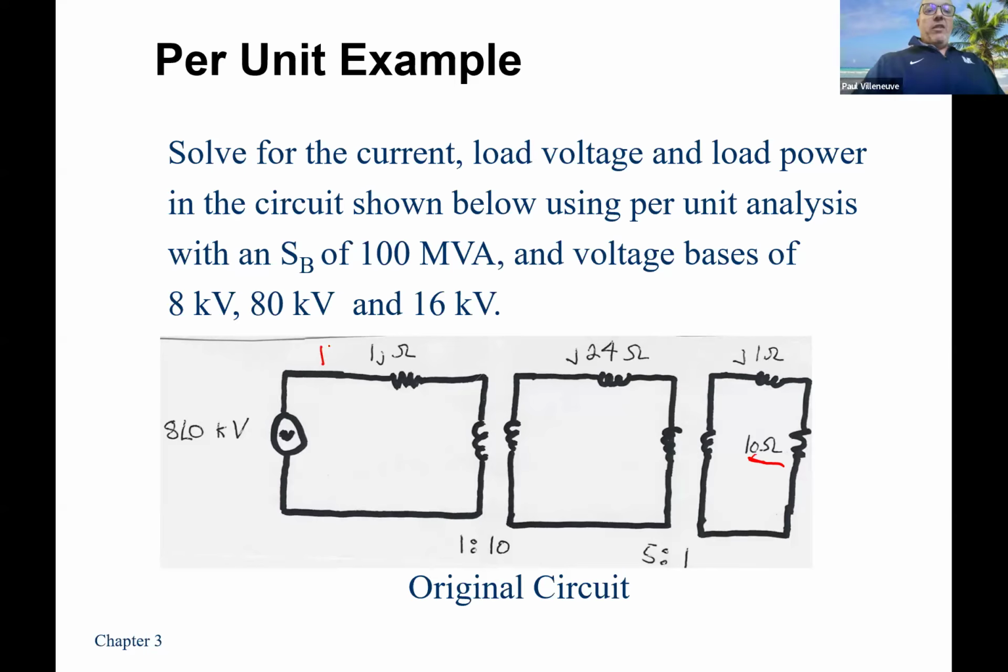No, because the current over here and the current over here, that's going to be 1/10 the current, isn't it? So even though I'm 24 times the impedance, the reactive power that's consumed in that line is going to drop way down because it's I squared times X. And I squared is 1/10 times 1/10. You're going to consume 1/100th of the power. So what if it's j24? It actually consumes less reactive power than those transformers. So it's not a big deal.